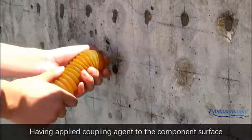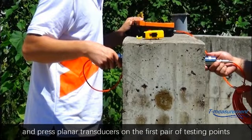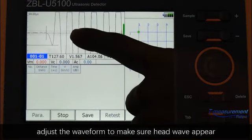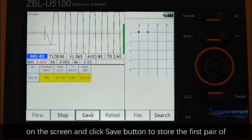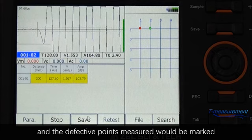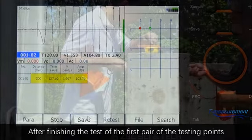Having applied the coupling agent to the component surface, press planar transducers on the first pair of testing points. Click the Sample button, adjust the waveform to make sure the head wave appears on the screen, and click the Save button to store the first pair of data as the waveform turns stable. The detailed data will be shown in the table at the lower left of the screen, and the testing points measured will be marked in red in the diagram on the right.